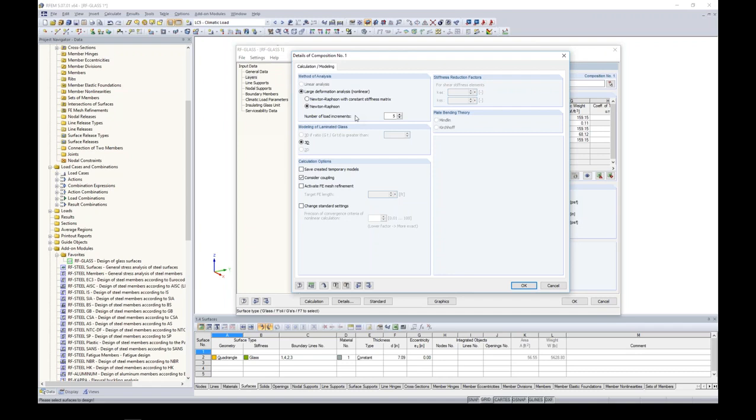It's the exact same thing with load increments. Maybe one load increment won't give you the correct results, but maybe 10 load increments is too many. It slows down your solve time, and your results aren't any different than what 5 load increments would have been. Default is 5 here, but you can certainly feel free to change this if you'd like.